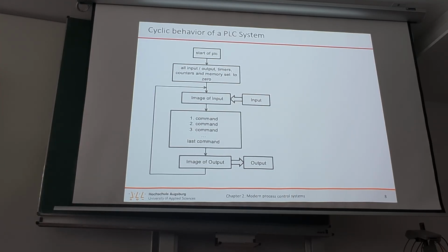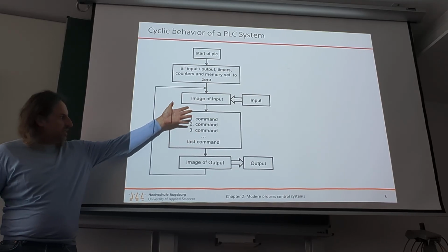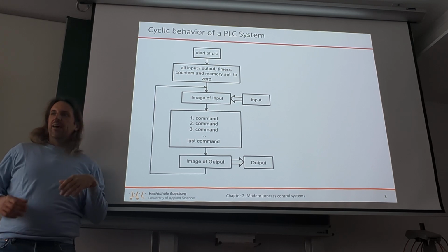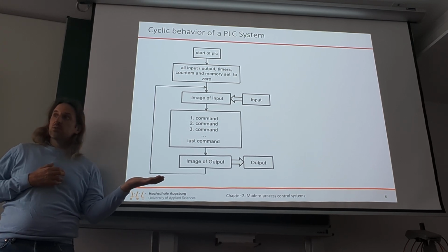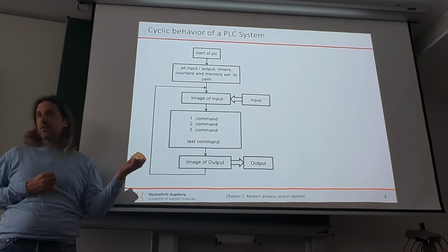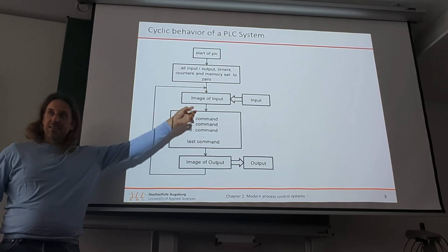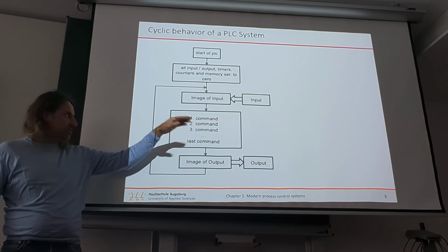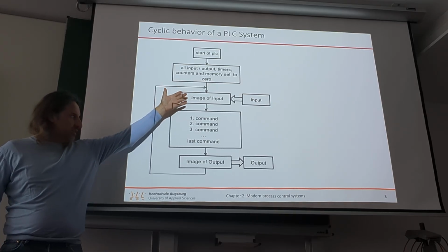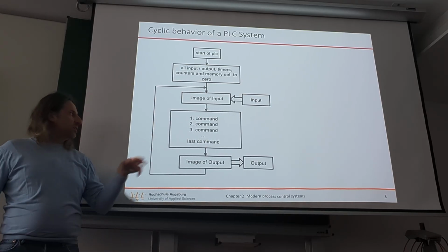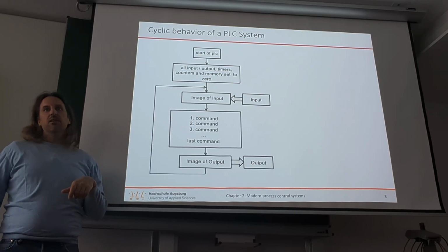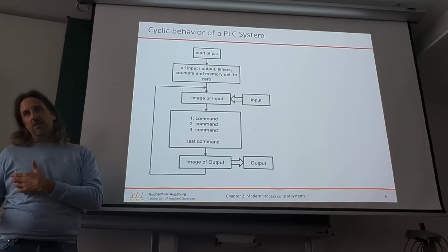Okay, so your program should be executed within this 1 to 10 milliseconds. So if you add a while loop to the system for infinite time, it would be bad for sure. You can't wait for keystrokes in here because you can't block the system. So that is the next difference while programming, besides working on the inputs and the outputs. If you create your logic, the logic must be non-blocking, because if you block the system, then you break the cycle.